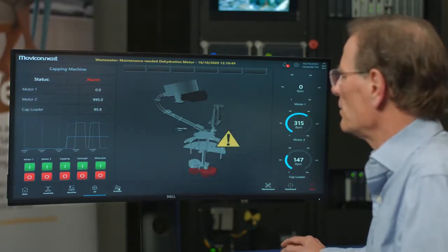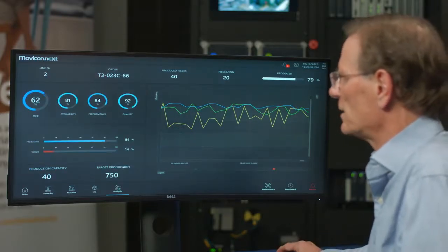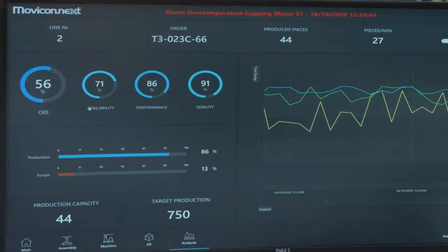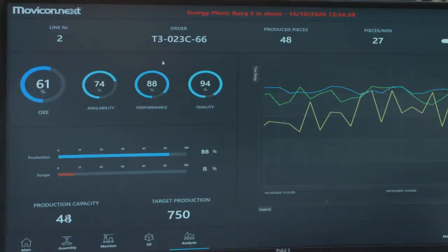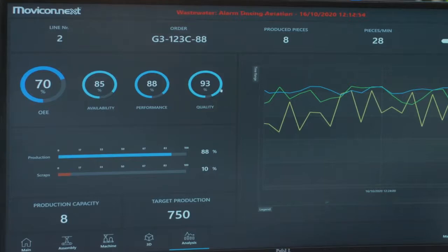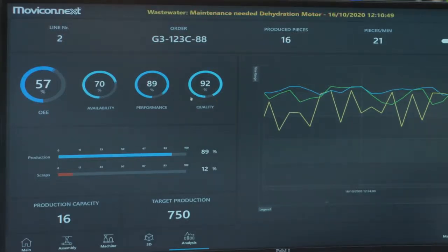From an analysis standpoint, here we have a capability called Overall Equipment Effectiveness, OEE. And here you're talking about, what is the availability of your equipment for production, what is its current performance, and what kind of quality am I seeing? Am I producing the right product at the right time in the volumes that I expect? Am I scrapping portions of the product, or is it all coming out well? This might even include the labels on the bottles. Are they skewed? In which case you have to maybe do some repair on it. So a lot of information is available through OEE.